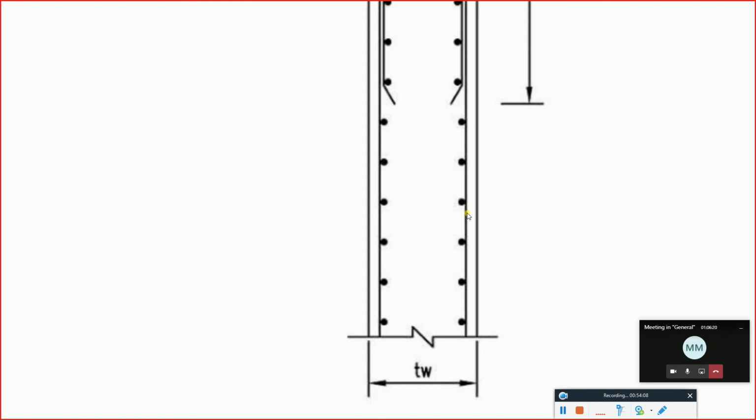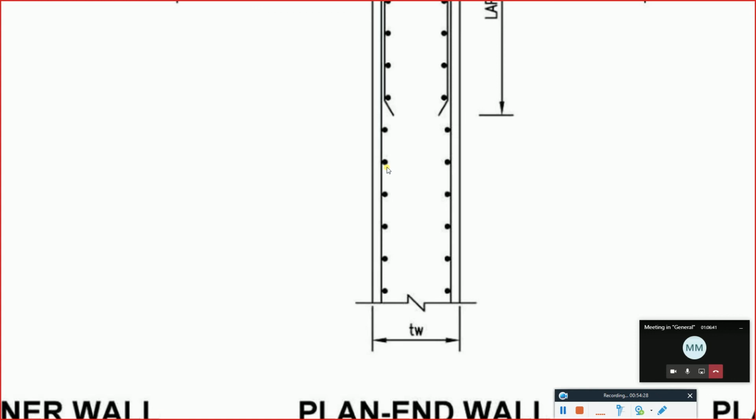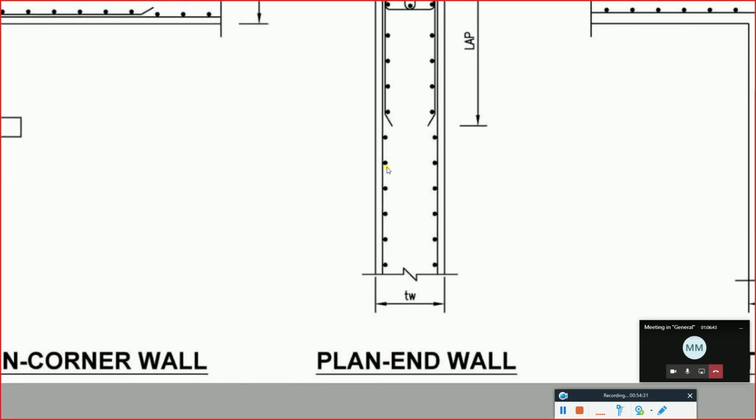So we have the main bar facing the sides. This is one side, this is another side. So this is the first main bar, this is the second main bar. And then we need to supply the secondary bars here. So it's like a slab, but it's flipped. Normally for a slab, the loading is coming from the top. That's why I'm providing horizontal reinforcement.